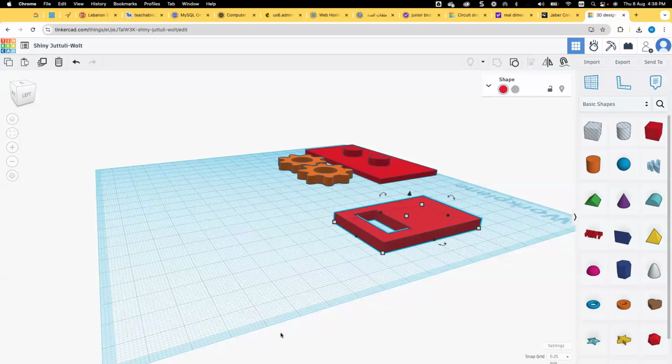So we have to make it horizontal. But the problem is, since I have the base and here there is an empty space, in order for the printer to print this in plastic, it should create a support here. And the support is made of plastic, so the result will not be really good, as you can see on this. You ask me why we took this model, and not maybe this model. Because this model, I can put it like this on the bed. I will print the wall and then the base without any support.